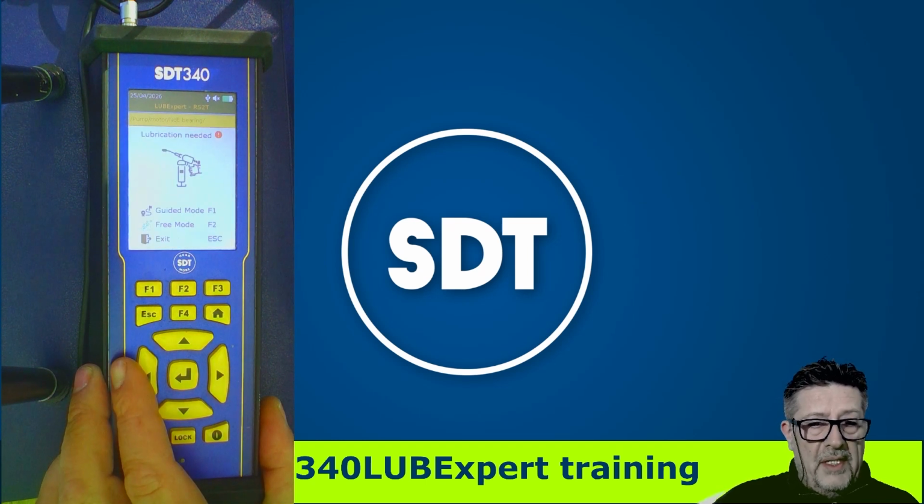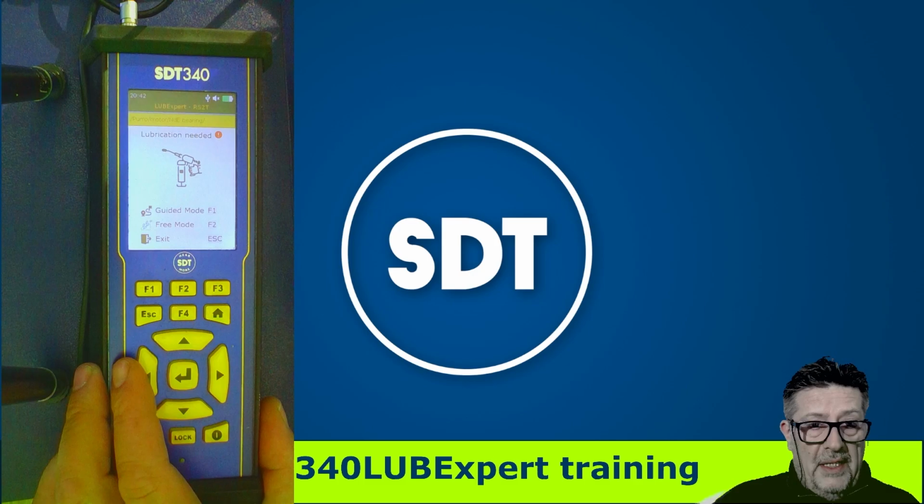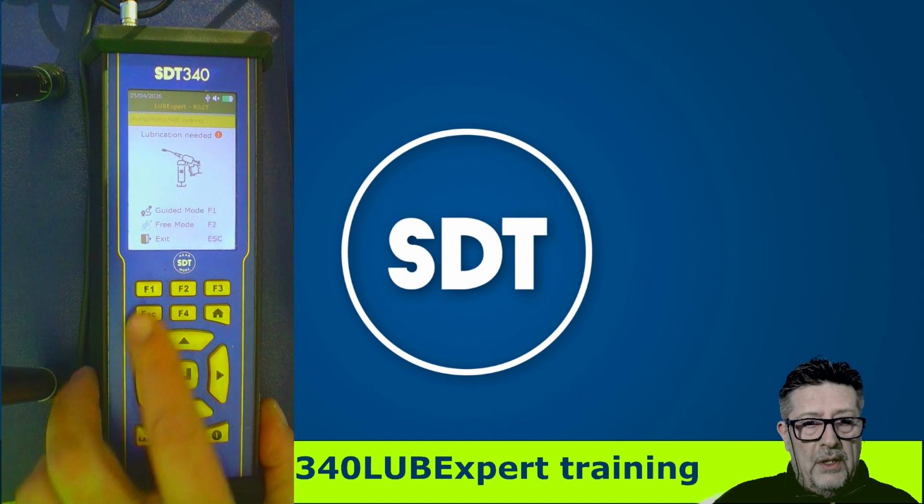Considering that I have the alarm assigned and alarm is triggered, I'm suggested that lubrication is needed. Alarm is triggered. So I can choose guided mode, free mode, or I can choose exit. If I choose to exit and not to lubricate, meaning ignore the alarm and recommendation, I will need to add a message, which will be set as a manual message. Yes, you have learned that in previous sessions. So there will be a tracing that I was suggested to lubricate, but I did not.